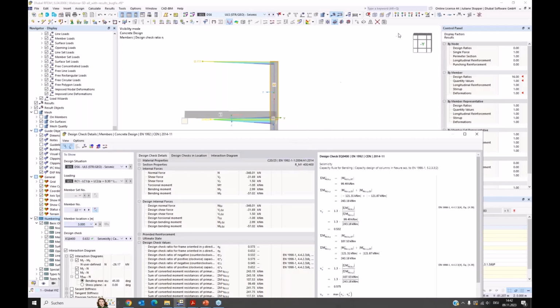And as we can see, we have the Y direction. So all these indices are dependent on the column. So I have the moment resistances around the local Y-axis of the column that are checked now first. And for this, around this node, around the Y-axis, so in this direction, the beam 67 is relevant.